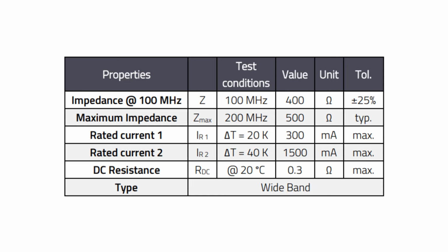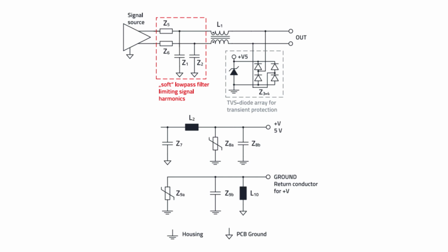To achieve broadband noise reduction, for the surface mount ferrite, the WE-CBF surface mount EMI suppression bead, we used 742792032. You can see that in our attached table. These are the electrical properties of our surface mount ferrite that we just mentioned. Our Z7 and Z8 are capacitors and varistors. The Z7 is a capacitor for low cutoff frequency filtering, and the Z8 is actually a surface mount varistor for transient protection.